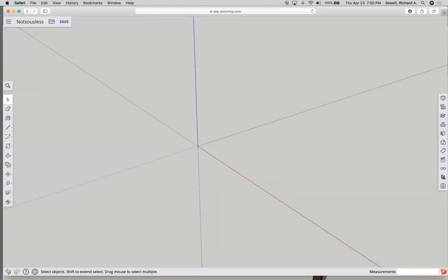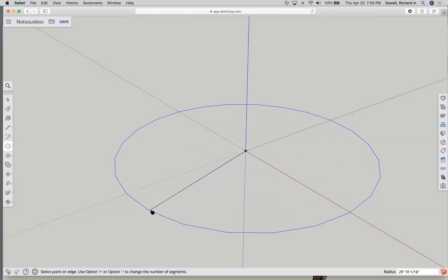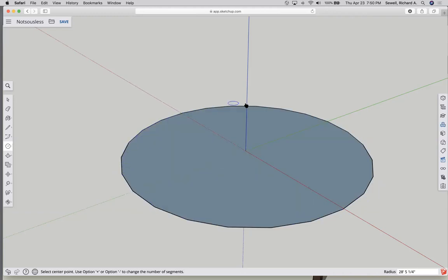One thing I will warn all of you is, let me show you one thing real quickly. One of the reasons why it isn't ideal for 3D printing, and that's the limitations with curves. I haven't shown you guys this yet, but if you see right away, I haven't even built the circle yet. If you look into my measurement box at the bottom where it used to say dimensions and measurements, it now says sides. That is the standard default of how many sides this circle is going to have. So if I click on the center and drag this circle out, you can see as I get bigger and bigger and bigger, it isn't really a circle at all. It's a bunch of segmented straight lines.